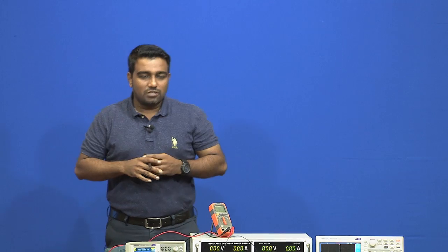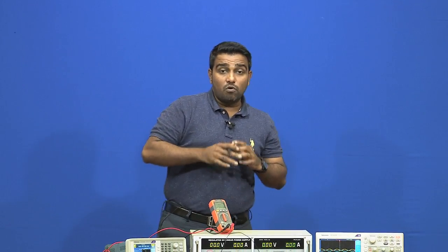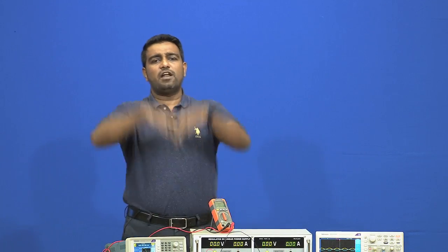But what we saw in the experiment is that even though there is infinite gain, right now we had a gain which is limited to about 10, but we can always increase the gain. Even though there is infinite gain, the output cannot reach an infinite value, but it is limited by the bias voltage. That means that one op amp cannot run the whole power or cannot generate that much power that the whole institute requires, right. So, always remember this, do not get confused that infinite gain means that we can have infinite voltage at the output.